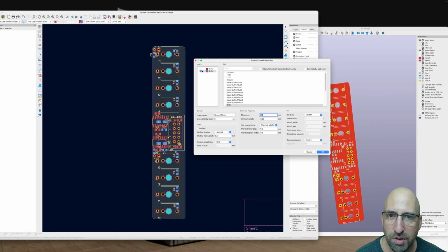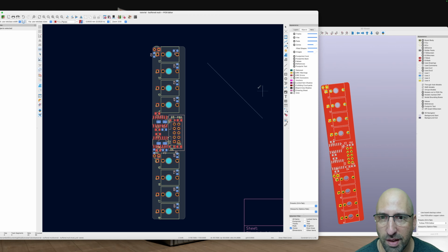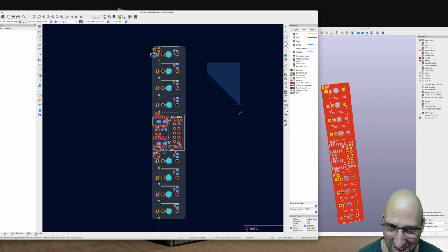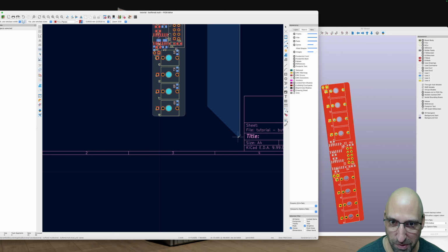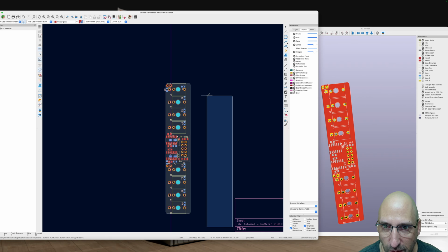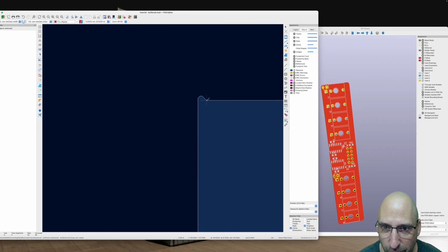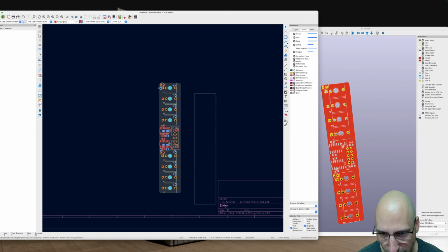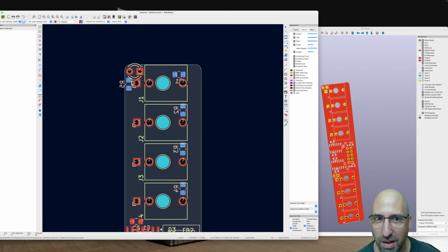Okay. So I'm just going to create a straight ground plane on the back copper. Solid fill always. Okay, that sounds wonderful. Do it. Okay, so now the problem is I've got this flipping cursor and it's way out away from the board. So let me just try something just for giggles. Yeah, I don't like that at all. So let me just nuke that. I'm going to come back here and start again.